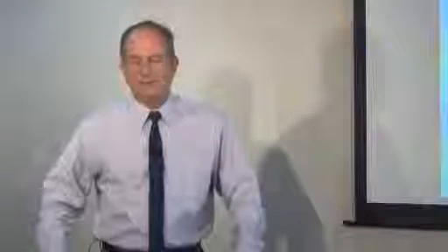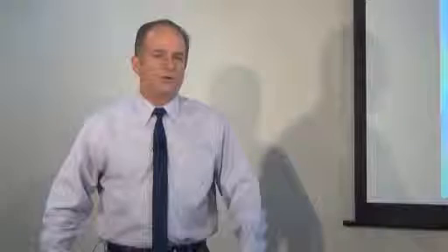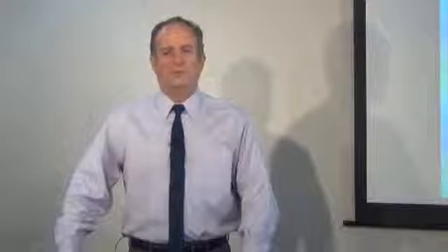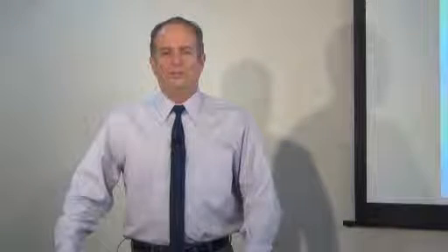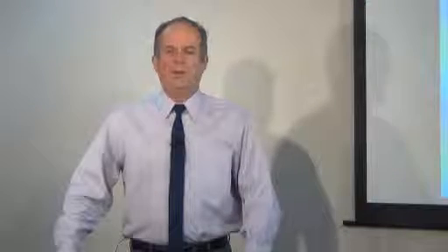We're going to talk a little bit about the per unit system. The per unit system is a simplification process of working with big numbers and trying to make them easier to work with. This is more of an engineering aspect of power system analysis, but it's very important. When you're on a per unit system, you have base voltages and you end up with a system that is a little easier to analyze. And if any of you are planning to become system operators or get into system engineering, you'll come across per unit system. And what we're doing is it's basically a ratio system.